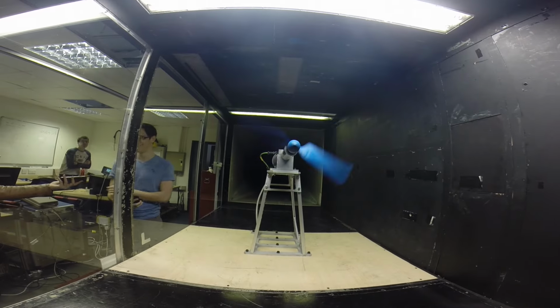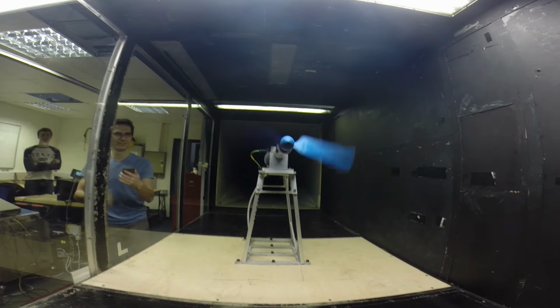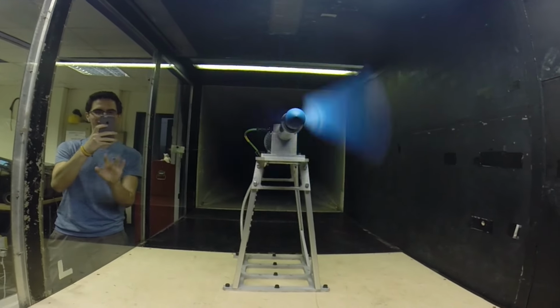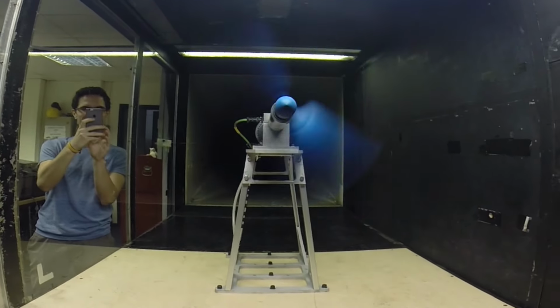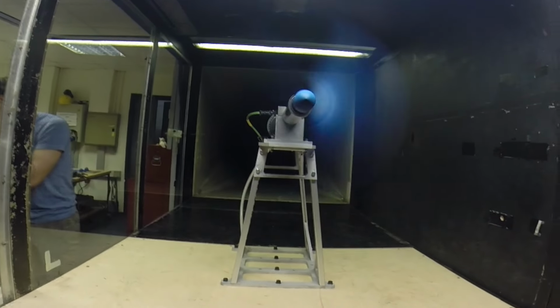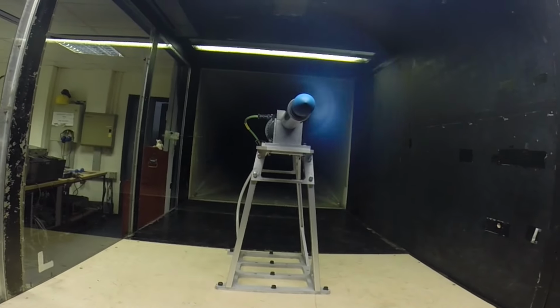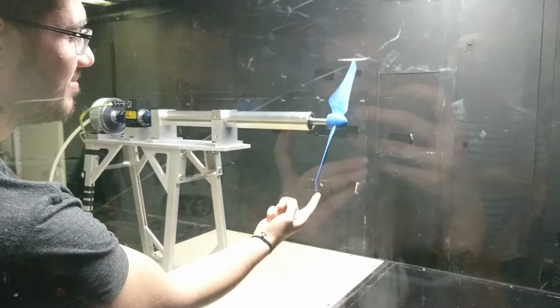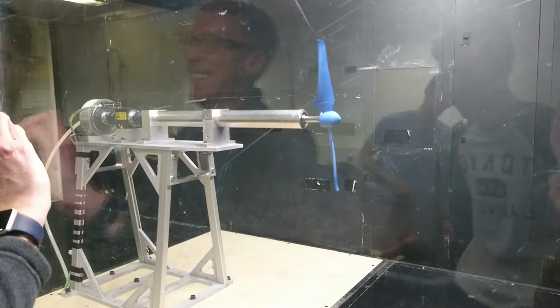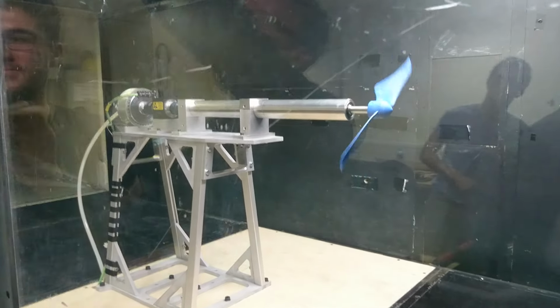Testing was the moment of truth for our design. The turbine was placed in the test section of the Donald Campbell wind tunnel and brought up to speed for wind velocities of 6, 8, 10 and 12 meters per second. The generated power was then measured. Despite it coming very close, the turbine was unable to self-start at 10 meters per second without a small perturbation. We suspected this could have been the case as the dimensions of the 3D printer limits the length and hence the surface area of the blades.